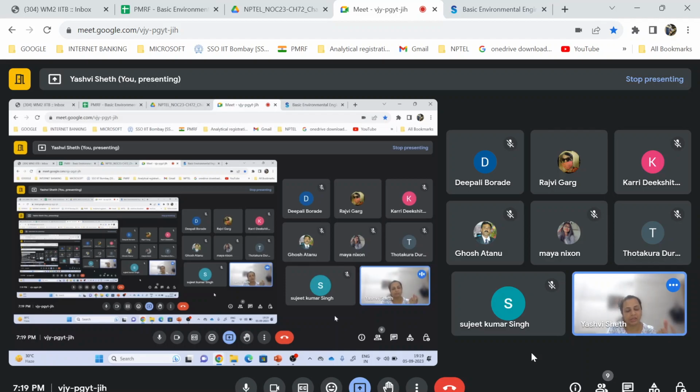For example, if you have bacteria in water, then ultrafiltration will be used, and here the pore size is such that the bacteria is bigger than the pore size. So bacteria will be restrained from passing through, and that is how you purify the water. What you see in lab filtration you can see with the naked eye. However, a similar phenomenon of size exclusion occurs, but you will not be able to see it. I hope this clears it up.